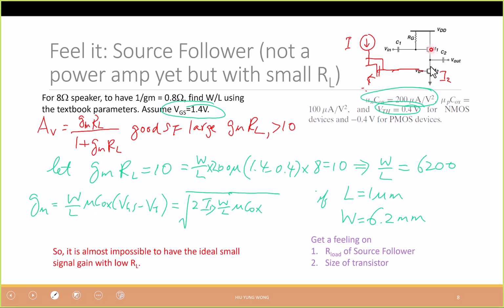Who thinks that this is I2? Assume they are connected to something. No. Look, we're just talking about DC bias. Should be I2. You know, if you did not learn about current mirror before, everyone would say I2. Because this one gives you another equation and you use it wrongly. This is just KCL, right? So if this is I2, what should be M1? It must be I2, no matter what area you have.